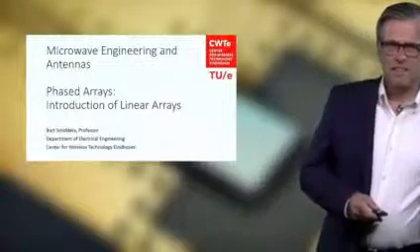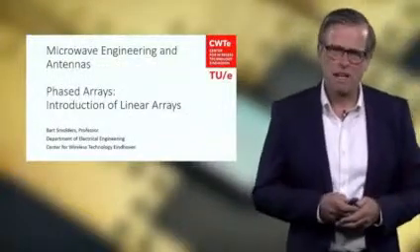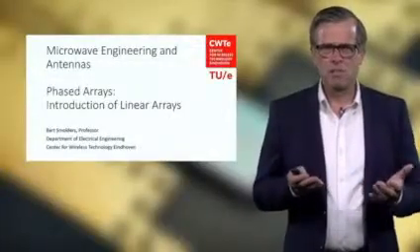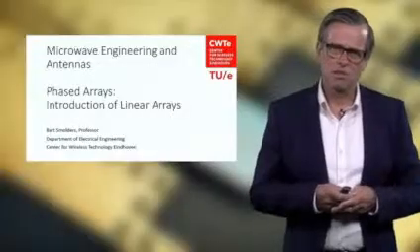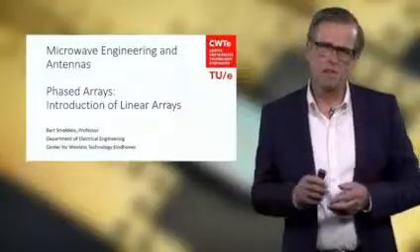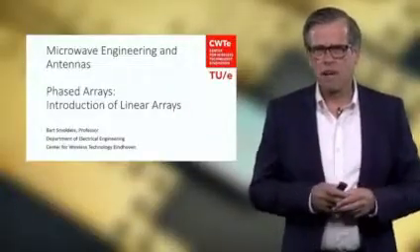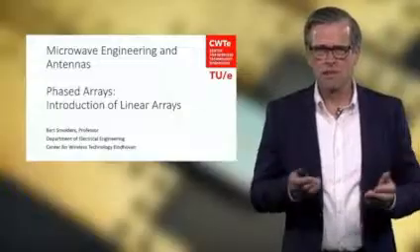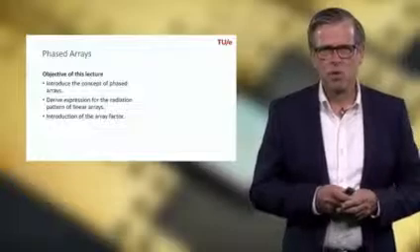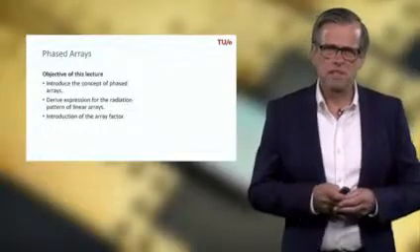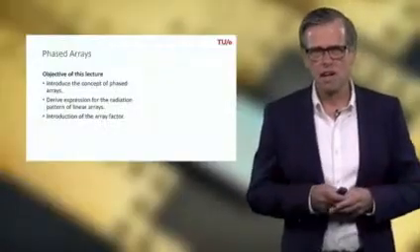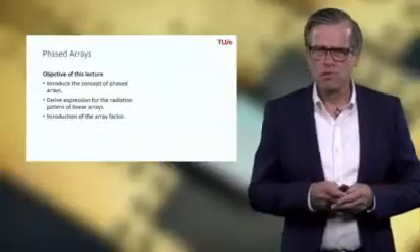Now today we're going to talk about phased arrays, and in particular I would like to introduce the concept using linear arrays. And up to now we didn't talk about antenna theory in order to be able to calculate the electric and magnetic field far away from the antenna. That will be done in the upcoming lectures, but the knowledge we have now already is enough to analyze linear arrays of isotropic elements. So the objective of this lecture will be first to introduce the concept of phased arrays. We're going to derive an expression for the radiation pattern of linear arrays using isotropic elements, and we're going to introduce the array factor.